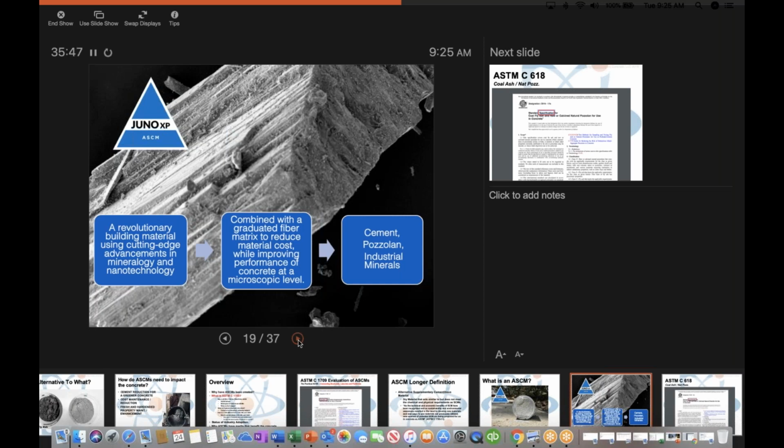So what we're ultimately seeing is somewhat of a molecular connection at the interfacial zone and an absorption of the catastrophic forces that would cause premature failure. And it can manifest in tensile or shear loads, and whether that's from actually putting loads on it from higher transportation loads or from the expansion of ASR, or alkali silica reactivity, at the interface of the aggregate. Next slide, please.